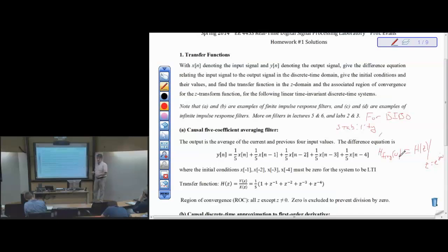And the third option is to take the inverse Z transform. It tells me how to do that, whether I want the causal or anti-causal version. Now, for this class, we will be causal. I will talk a couple of times about anti-causal processing, but for the most part, we will be causal. So when you say include the unit circle, does that mean that's greater than or equal to? Yes, the unit circle must be included. It cannot be excluded.